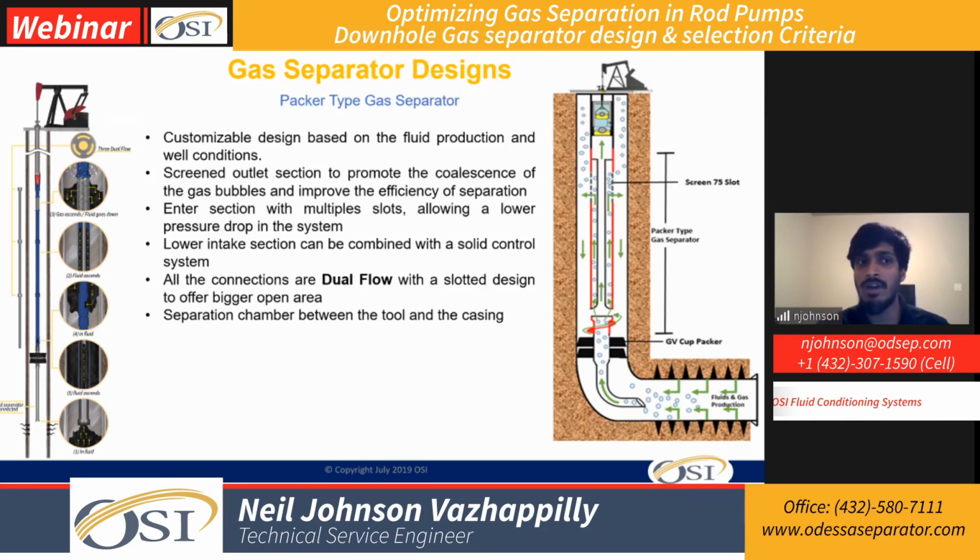So the total amount of fluid that can be stored, like I mentioned, is 7.27 cubic foot in this section, right? Convert that 100 barrels per day, we get about 0.35 gallons of fluid per stroke, which gives us, just in this volume, an additional 154 strokes for the pump to not run dry, in conditions like I mentioned before. So that is a big advantage of having a 72-foot tool.